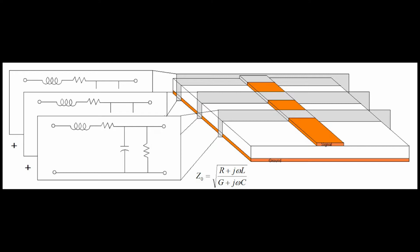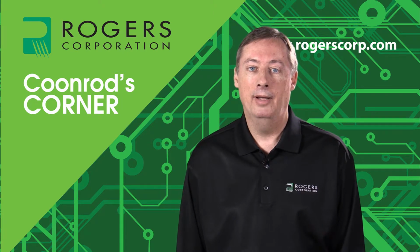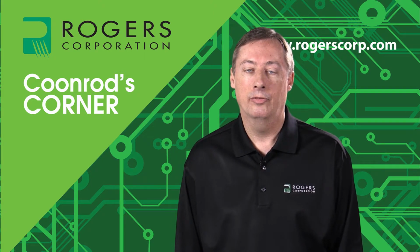Now the formula I've shown here is similar to the last formula, but this formula actually has loss characteristics included. So the R is loss characteristics related to the conductor, and G is loss characteristics related to the dielectric material, so dielectric losses. These basic impedance formulas are really used for reference, and it's good to keep them in mind when you're going through design or even troubleshooting, just to understand the relationship. And in a few minutes I'll go through that in a little more detail to give you a feel for how you can use these formulas.